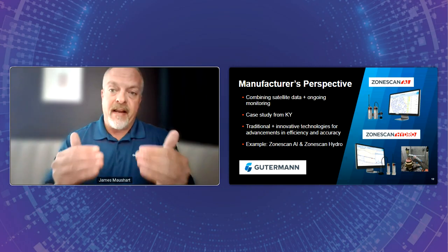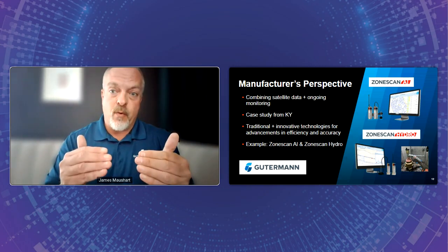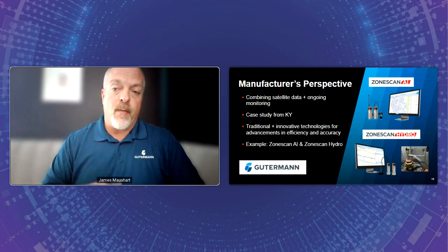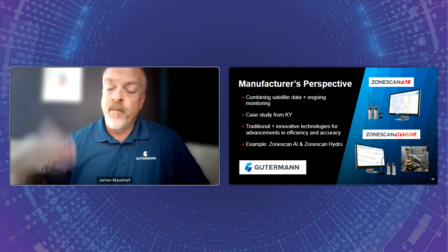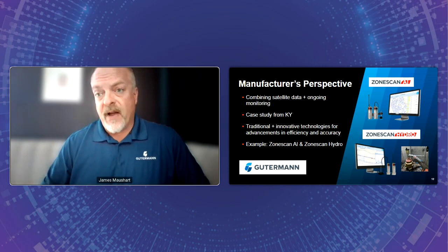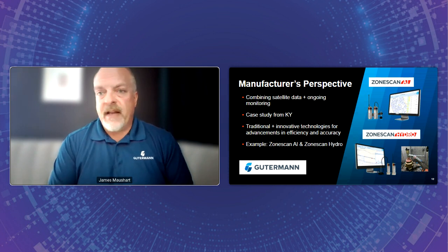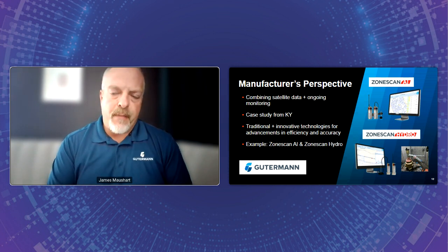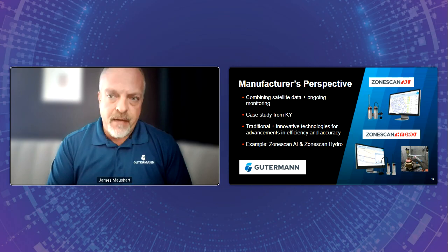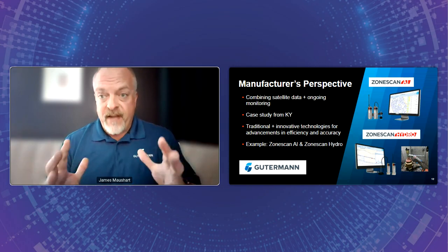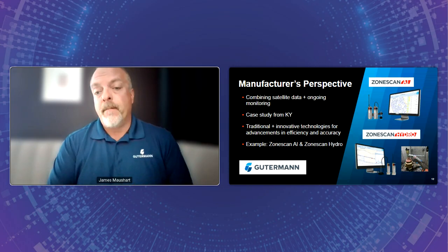Now we're getting really specific with correlation, to the point where you can almost send out a field tech with a ground microphone to verify what you're coming up with. I always say with the 3 steps, survey gets you on the street, a correlator gets you in the ballpark, and a ground mic puts you in the seat. So very fast, getting you where you need to be.